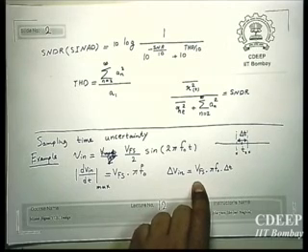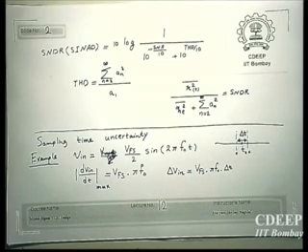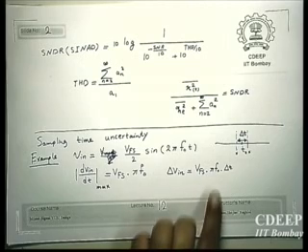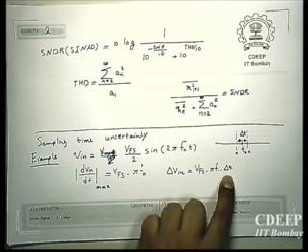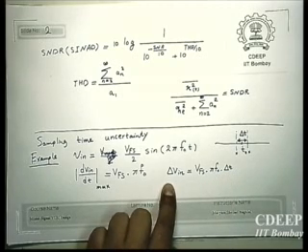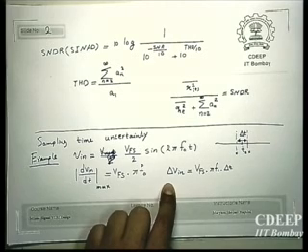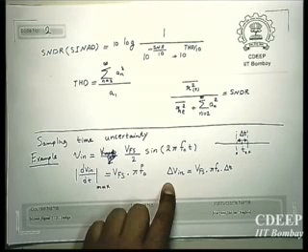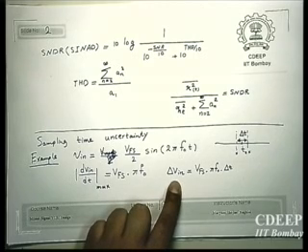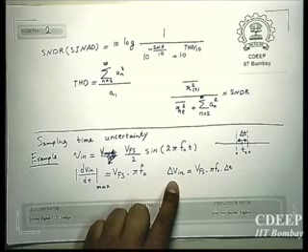right? So what is the effect? If you have ambiguity or uncertainty in the sampling time, it gets translated to error. Your input voltage was supposed to be something when sampled, and now its value changes. In fact, you have uncertainty in the voltage domain now.